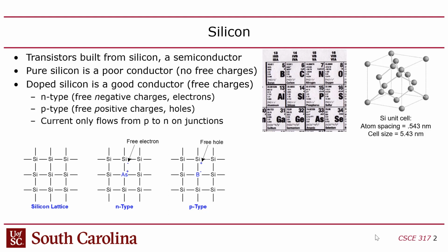But there's also the other type of charge carrier that is opposite of the one that you deliberately doped with. So for instance, if you dope with arsenic, that's column 5, that's going to give you electrons as the majority charge carriers. You also end up with minority carriers, some holes in there as well. Okay? I'll revisit that in a minute.